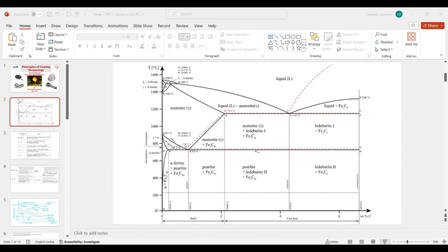Those samples will have very high hardness values, if you create a sheet from your ingot with the help of cold rolling. That cold rolled sheet cannot be directly used for deformation processes.